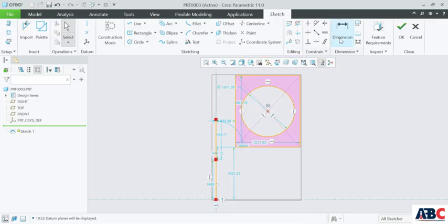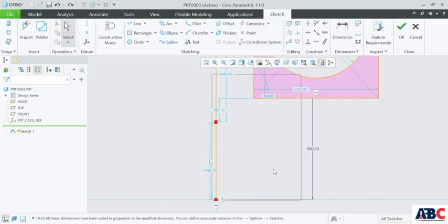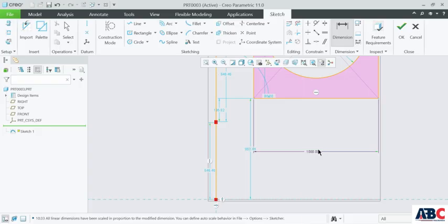So now we will see the dimension. For applying a dimension, select the lines, second, and click the MB2 button, the scroll wheel. You can add a dimension here. You will be seeing this again. Go to the dimension, select the entities, then wherever you want a dimension, press the MB2 button or scroll wheel button. So this is how you can create a dimension.